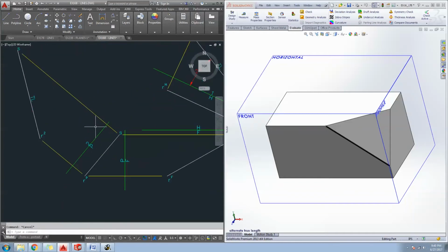That's all nice and neat right there. So now that that guy's in true length, we're ready to pick up a dimension. And the reason I know that is because I want a profile true angle. I have an edge view of the profile. Again, these folding lines represent edge views, and I have the true length of a line.